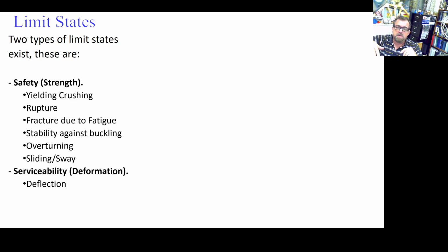Now if it's plaster, and it's the same deflection, then the plaster is going to crack. Would you like to see those cracks? Would you feel comfortable living in a place with cracks due to deflection? No. Even if you're an engineer and you know that it's safe, it's uncomfortable. That's what I call comfort related.